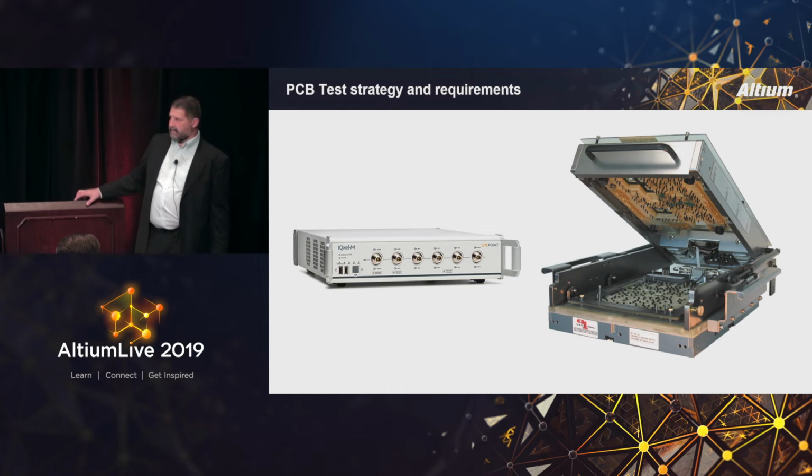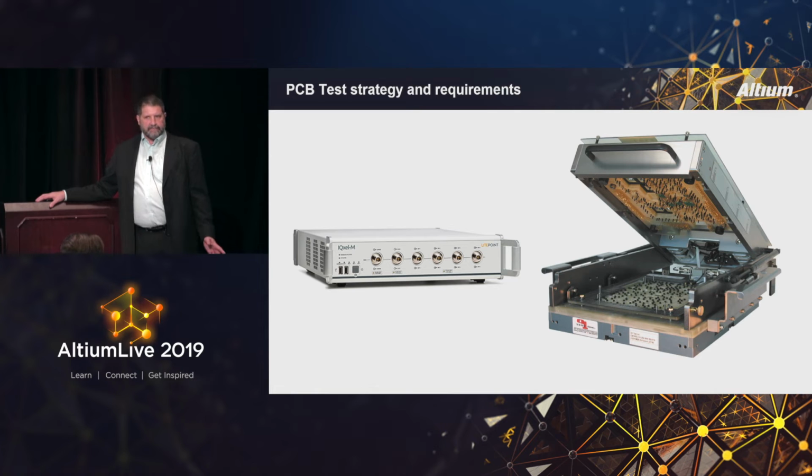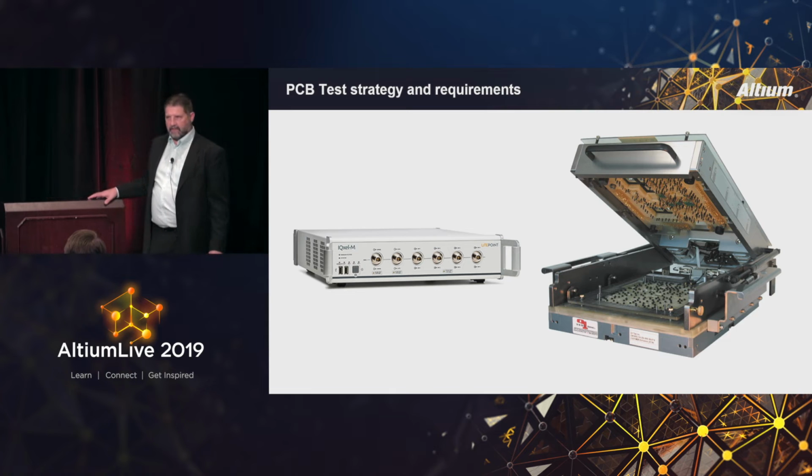Typically not. No, you don't want to do that because those are going to vary a lot. And that could be quite costly. We generally don't do that unless it's some weird thing that can't be tested any other way. We generally try to shy away from that because that's going to involve cantilevers and much more expensive mechanical fixturing. When they do these pins, they just want to drill it, insert a pin, put a wire in, put the wire to the computer. You can even open up the solder mask on wide traces with broken traces, right? Yeah, that can be done, or you can put a bead of paste down as well. That's another very fine pitch type of test method.